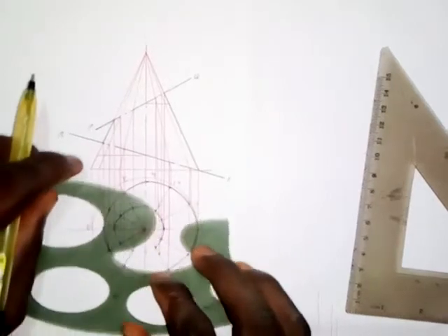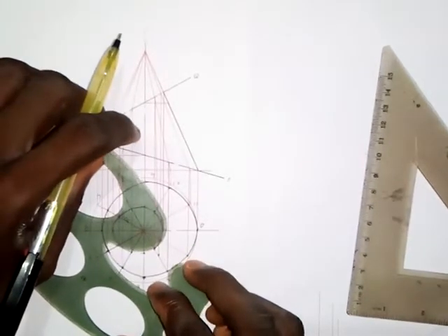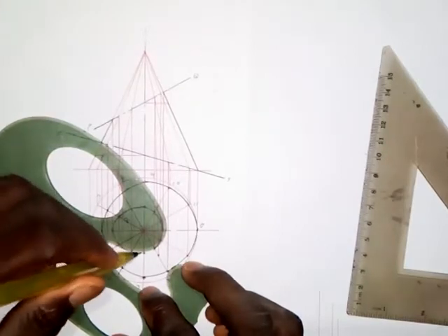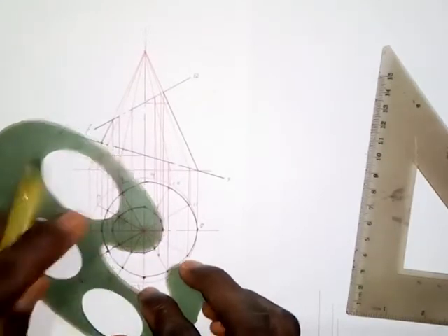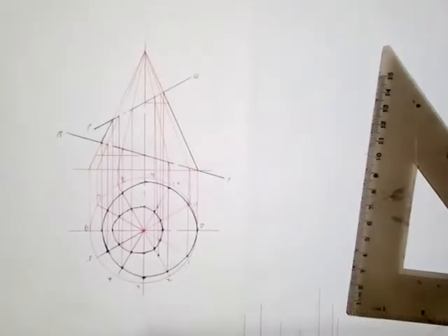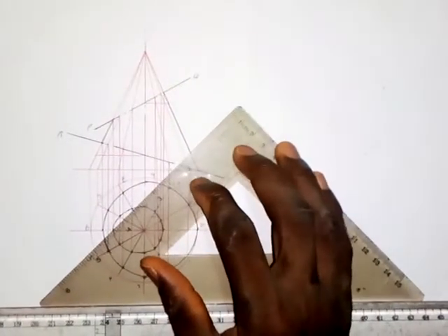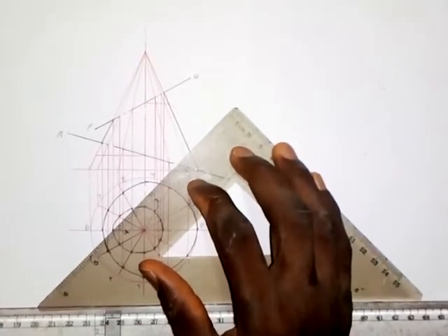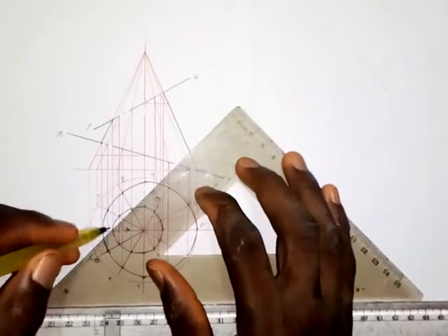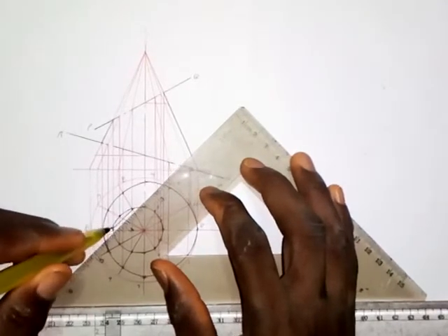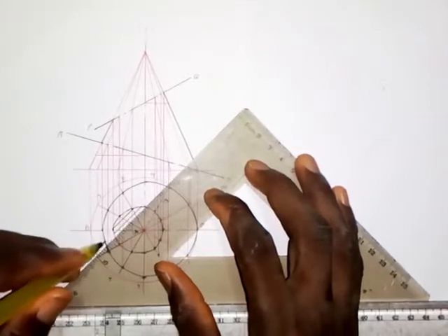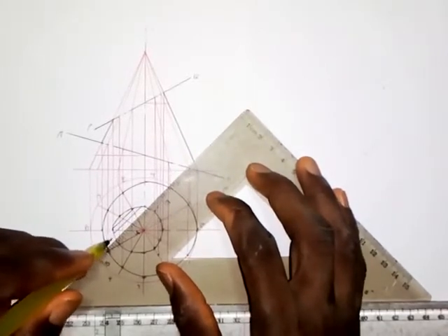Okay, so don't forget what we are trying to do here is to draw the complete plan. So now, for this one that we have done, I'm going to arch this surface because this surface will look rough by the time we remove this part. So I draw this line, putting the arching lines here to show the roughness of the surface.